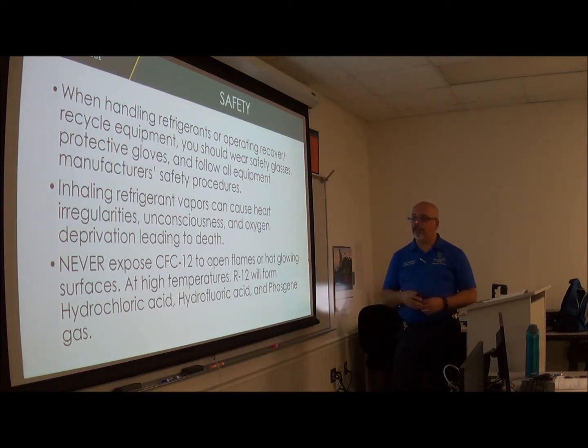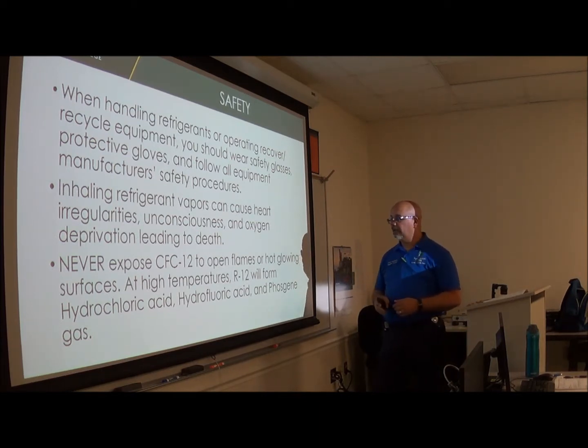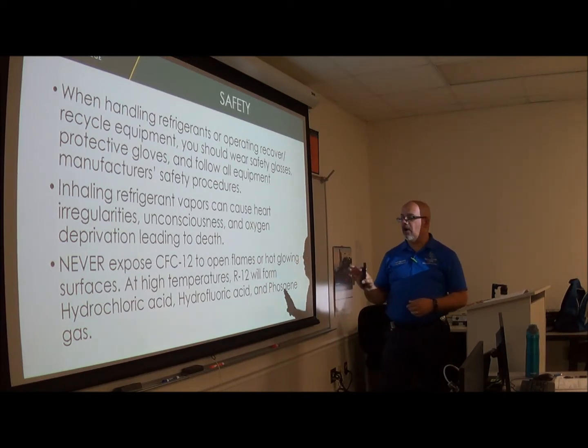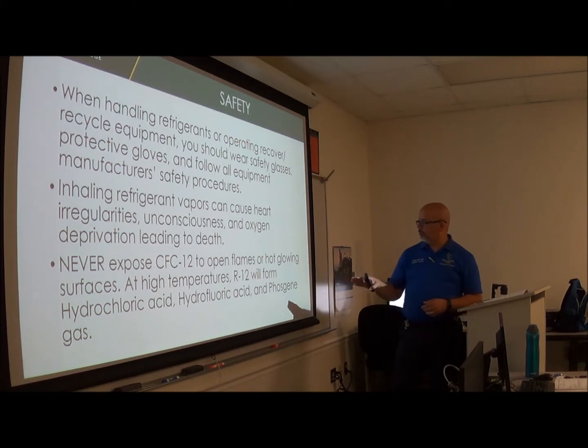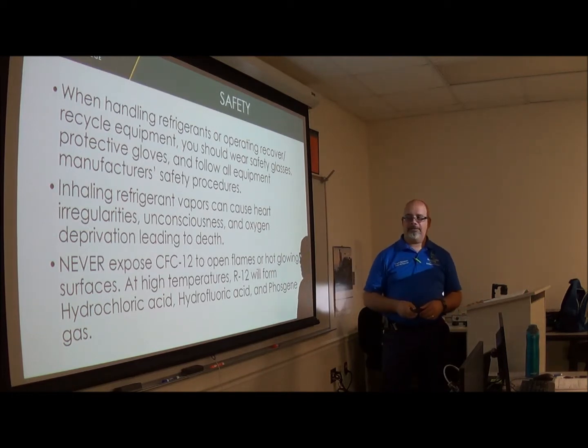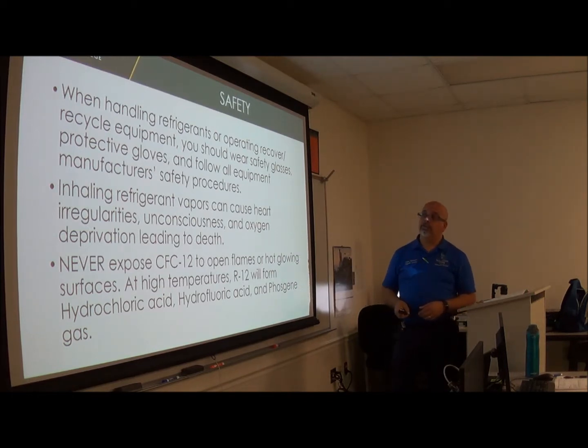Never expose CFC-12 to open flames or hot glowing surfaces. At high temperatures, R12 will form hydrochloric acid, hydrofluoric acid, and phosgene gas. Okay? So be a scientist along with being an automotive mechanic.